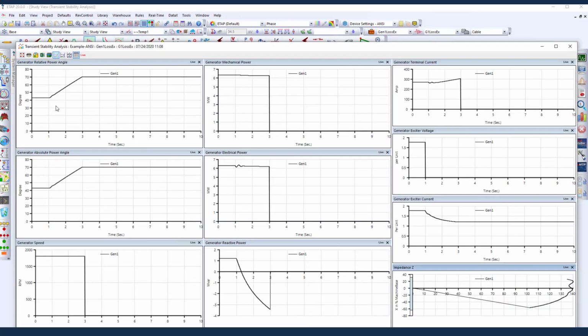In this case, again, during the time that we lost excitation, the generator angle increased, and you see that the generator starts absorbing lots of reactive power. Basically your machine, which is a synchronous machine, gets converted into an asynchronous machine. The reactance goes all the way down to here up to 3 seconds, when we trip, then the reactance becomes 0 or infinity. In that sense, that is not valid anymore. So you can see the trajectory of the reactance that is important for several protection settings. You can see how the system behaves.